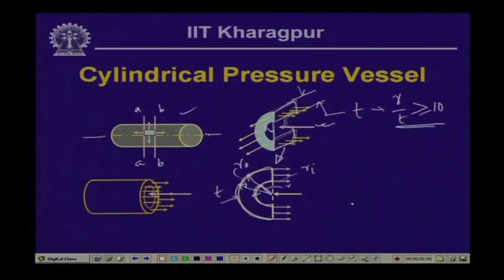And the stresses that will be acting, if we take an element on the surface of this cylinder, we have stresses acting in this form, stresses acting in the circumferential direction. Let us call this sigma 1, and the stress acting in the longitudinal direction, let us call that sigma 2. So, in the circumferential direction, the stress acting is sigma 1. Now, let us say the resulting force acting here is P, this also is P, and the content is exerting pressure on this side.